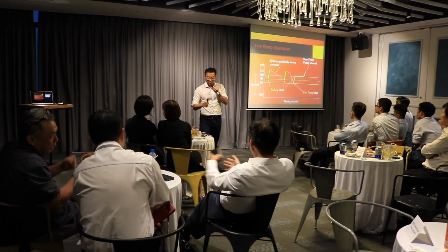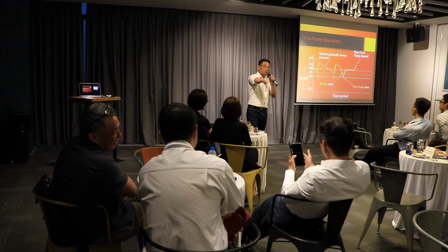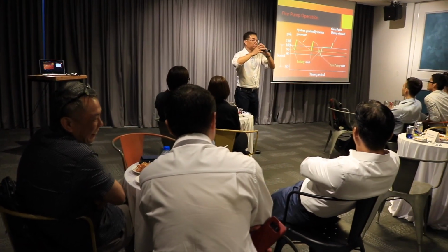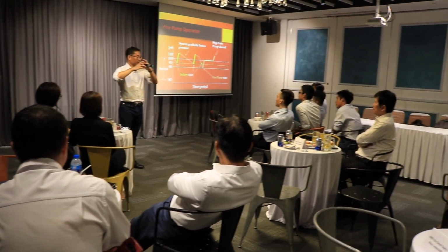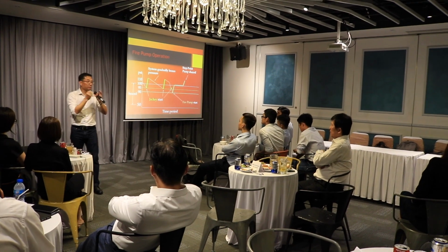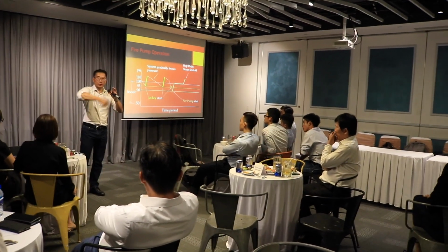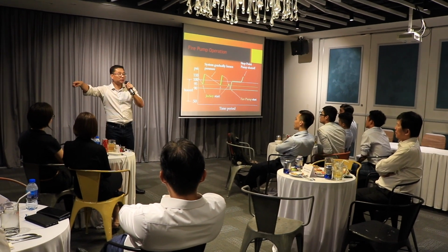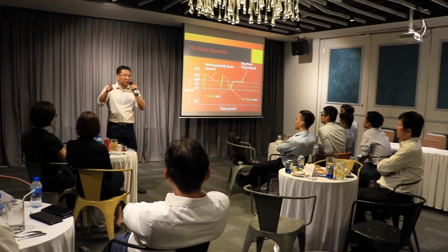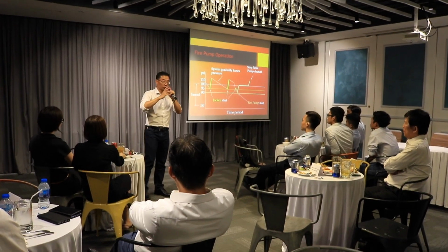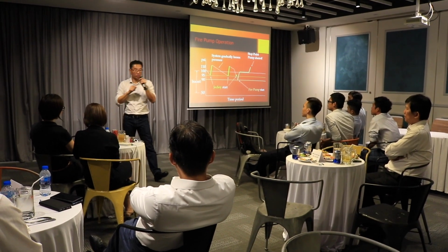Mechanical failure: we have had a pump that we installed for over 10 years where the coupling broke. My control panel sends the signal that it is drawing current, and the motor is still running at 30%. I cannot switch over because there's no interlocking. So the fire burned because my coupling broke. So you must have an interlocking.